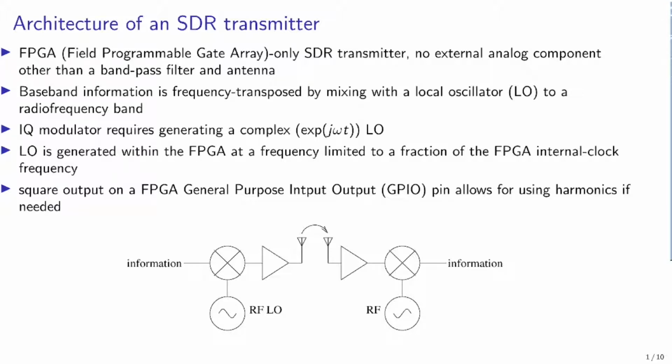Now, as a quick reminder of the reason for radio frequency communication, we wish to convey information from one speaker to the other speaker. In order to share the spectrum and to have antenna dimensions much smaller than the baseband signal, here this information is centered on 0 Hz, we transpose this information onto an intermediate radio frequency carrier that will allow us to share the spectrum between multiple users. This intermediate step of imprinting the information onto the radio frequency wave is called modulation.